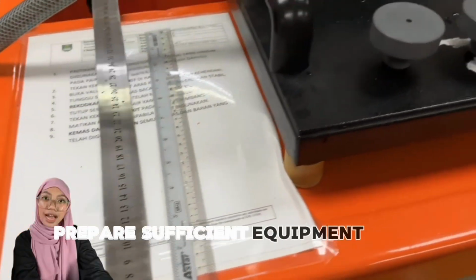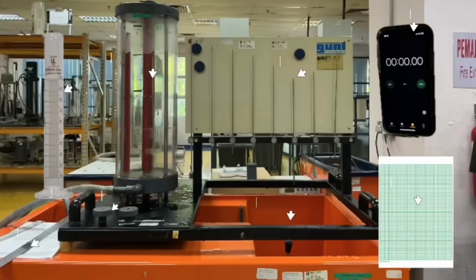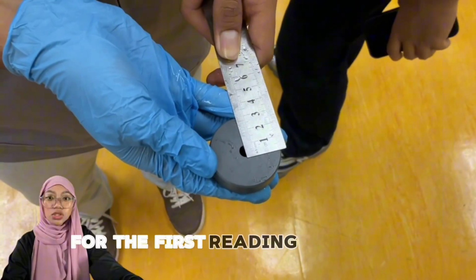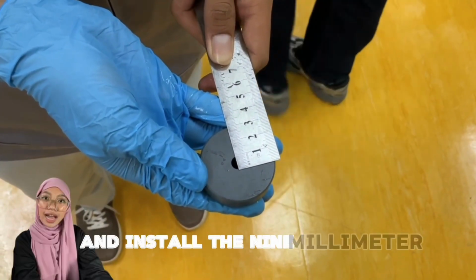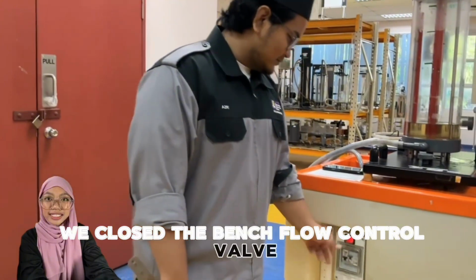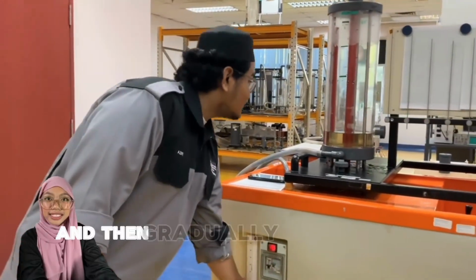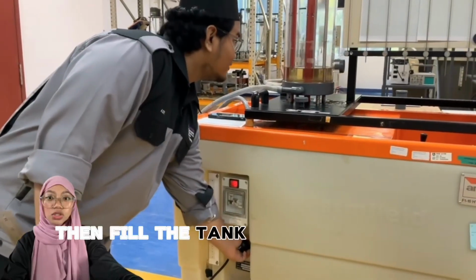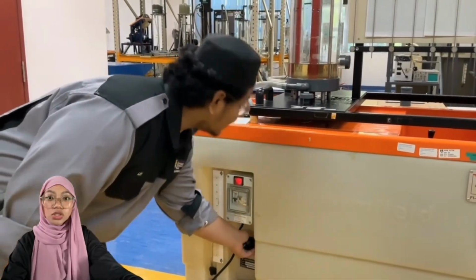Prepare sufficient equipment before starting the experiment. For the first reading, we measured and installed the 9 mm orifice in the fitting on the right hand side of the head tank. We closed the bench flow control valve, switched on the pump and then gradually opened the bench flow control valve. Then fill the tank until 35 cm.